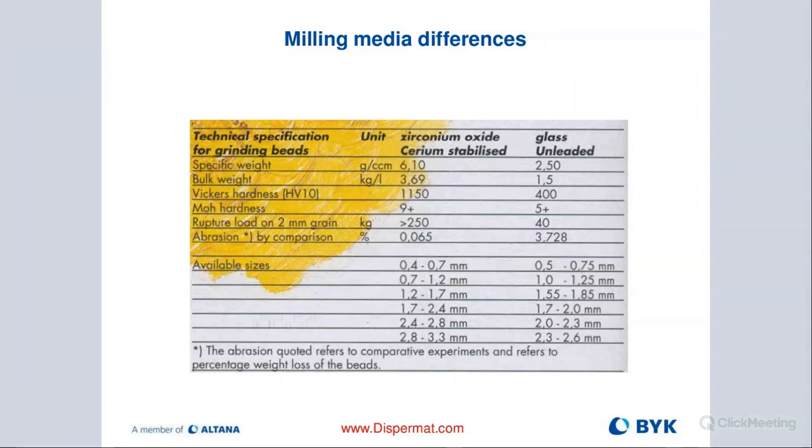So basically, these are things that you should remember. Depending on what you're trying to do, steel beads are not great either, especially when you talk coatings or new end-use markets where color stability is critical. By using steel, you're causing the metal of the bead to wear over time, and also the milling components, the disc, the rotor, all of that.